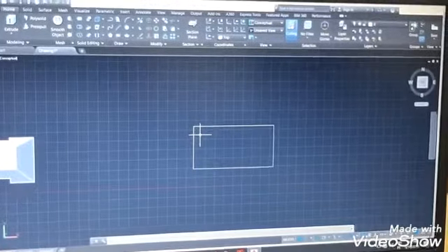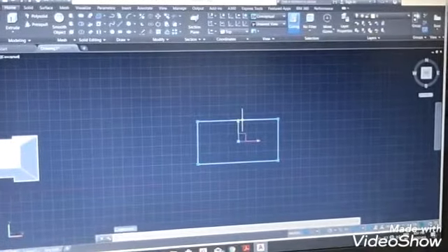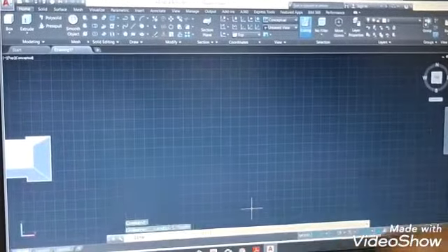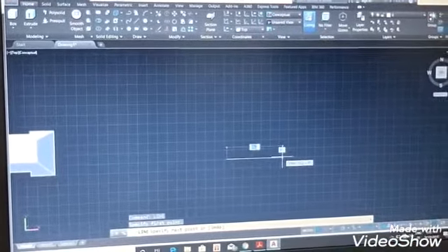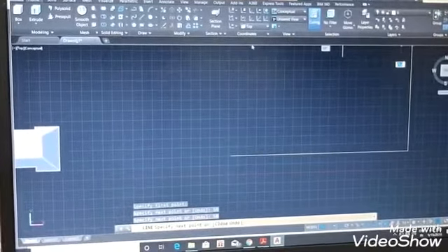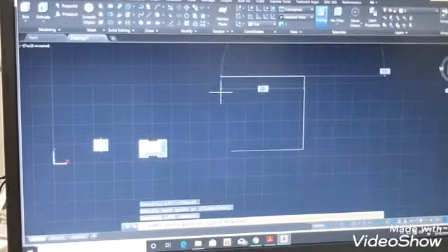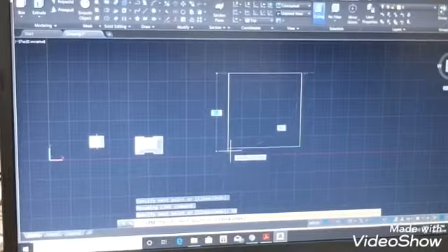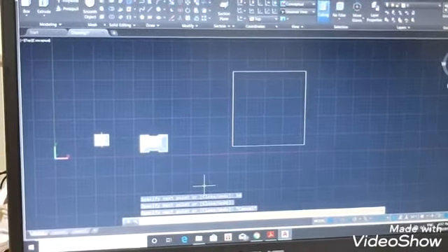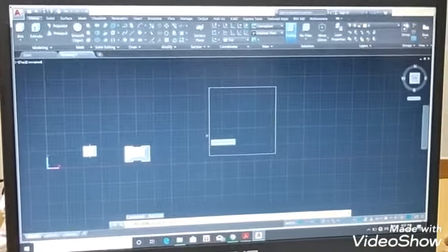I'm going to draw a square pyramid now. In order to draw a square pyramid, I will construct a square using the line command. First point, let it be 50 mm. This also be 50. Use the region command to make it a single entity.